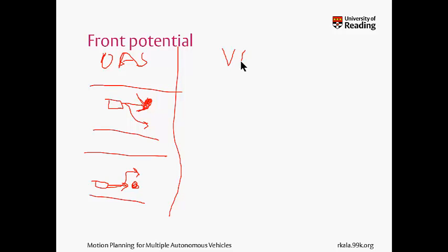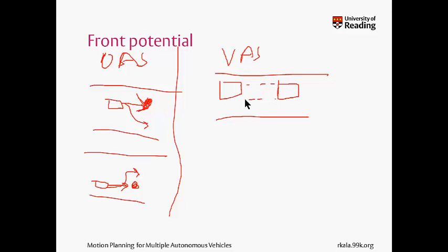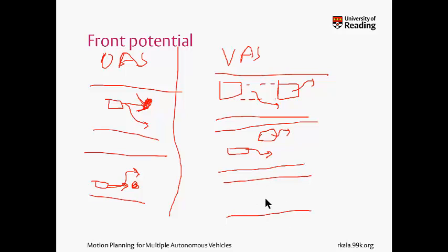And the other is the vehicle avoidance strategy, where I see the same scenario, but in place of an obstacle there is a vehicle which lies in front. If I'm exactly behind, then I will follow the overtake from the right strategy, and the converse strategy would be used for this. It'll dip leftward for cooperation. If I am more on the right and this is more on the left, I'll overtake from the right and this will dip leftward. And if the converse happens, I am more on the left and this is more on the right, I'll overtake from the left.